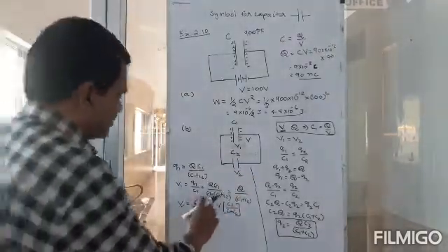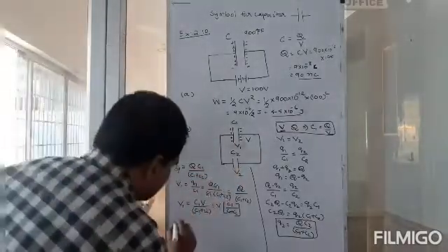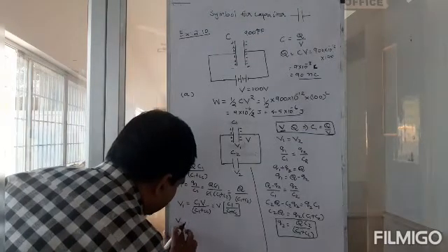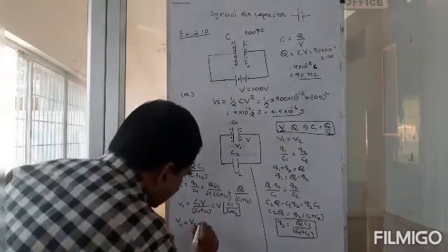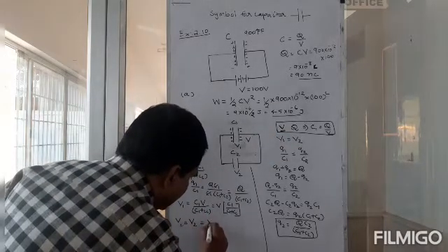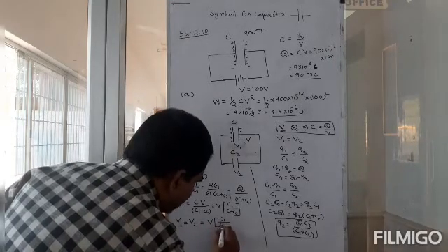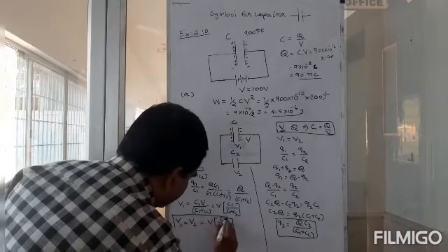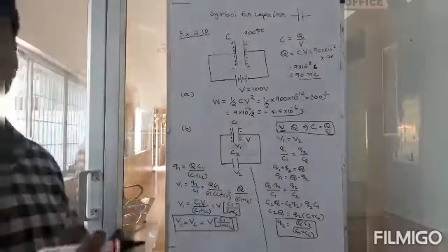So this is a very important expression. See, finally V1 will be equal to V2, right? So V1 final voltage will be like this. V1, which is going to be equal to V2 finally, and it must be equal to V into C1 by (C1 plus C2). So very important expression. So remember this.